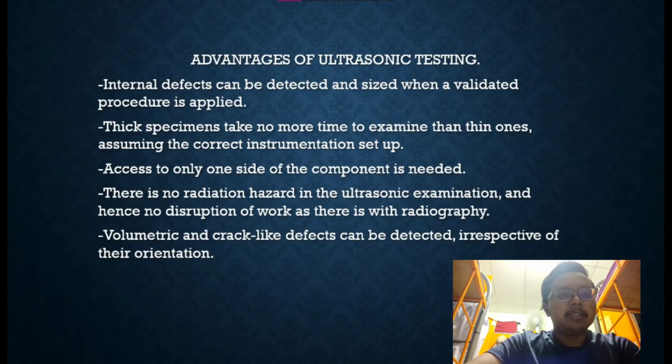The third one is that access to only one side of the component is needed. Next, there is no radiation hazard in ultrasonic testing, and hence no disruption of work as in radiographic testing. The last advantage is that volumetric and crack-like defects can be detected irrespective of their orientation.